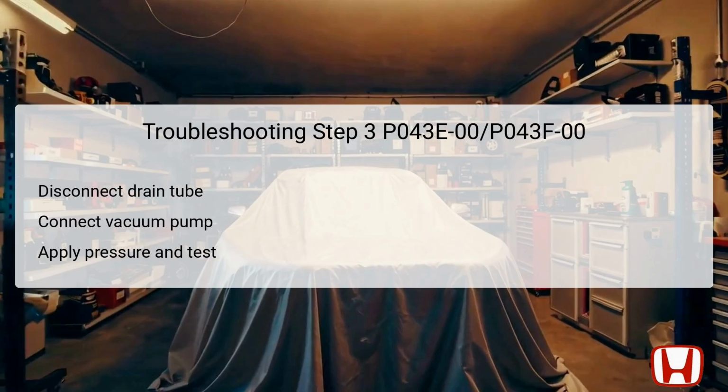In this troubleshooting step, disconnection of the drain tube from the evap leak check module is required as a part of the diagnostic process. Following this, the next action is to connect a vacuum pump equipped with a gauge to the drain tube. This setup allows for the application of pressure to test the integrity of the system.